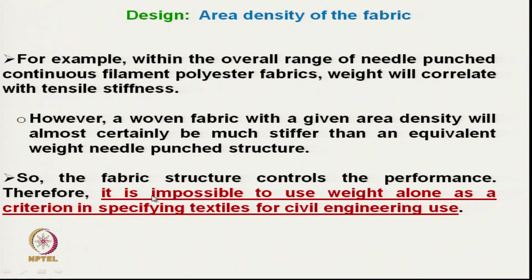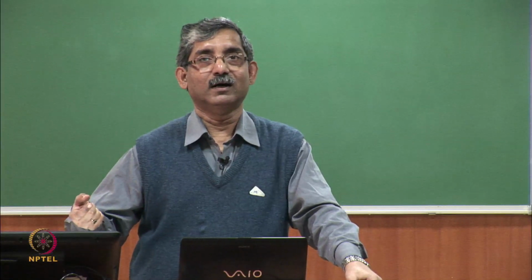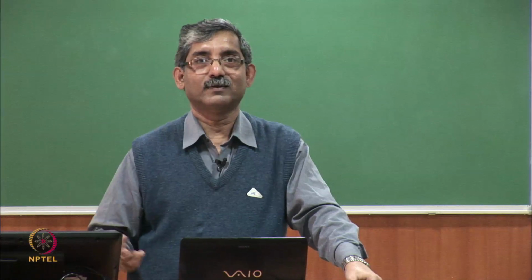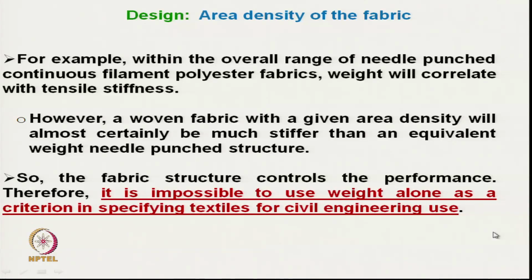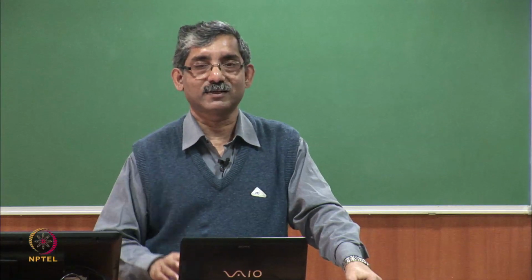So, the fabric structure controls the performance. Therefore, it is impossible to use weight alone as a criteria in specifying textile for civil engineering use. So, we cannot say X mass per unit area you can use for a particular application, for say reinforcing application or soil stabilization application.